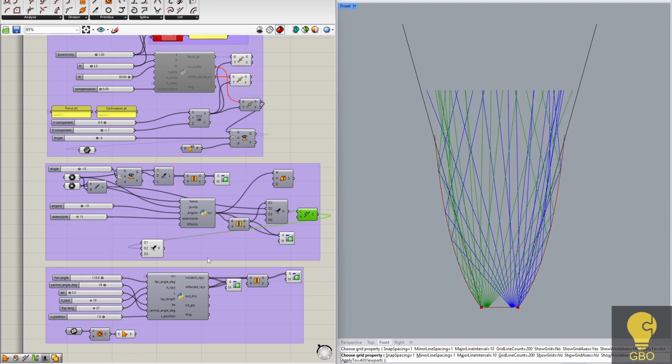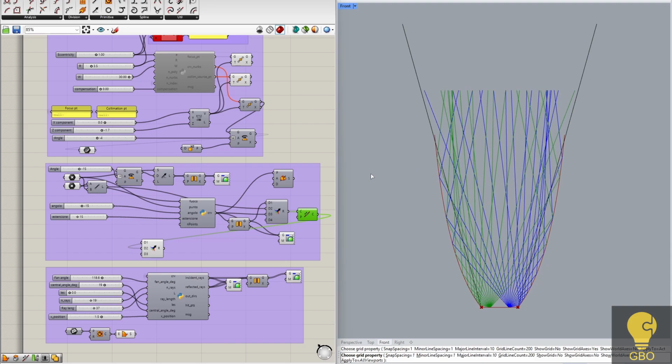It is worth being precise about what those escaping rays mean, because it would be easy to conclude that the device is approximate by construction, and it's not. In 2 dimensions, the full untruncated profile is exact for the design condition it was built for. Every ray from the source lives within the acceptance angle. The rays that escape in our simulation escape because we cut the profile short. That cut is a deliberate engineering choice rather than an oversight.